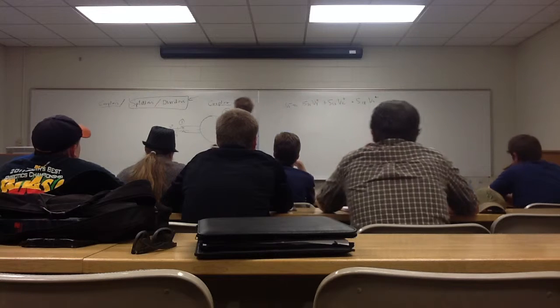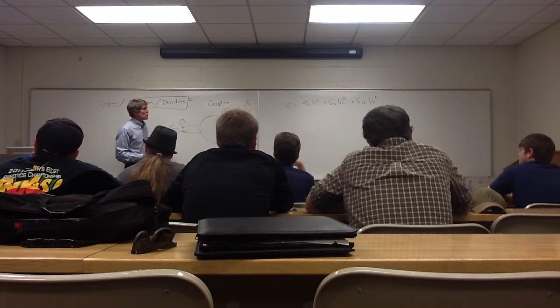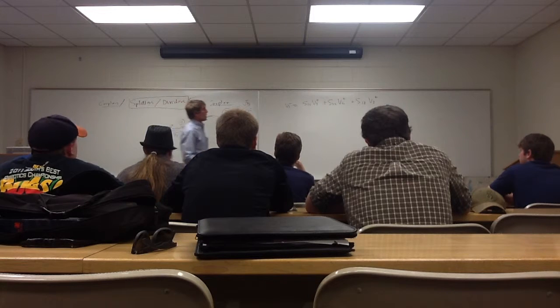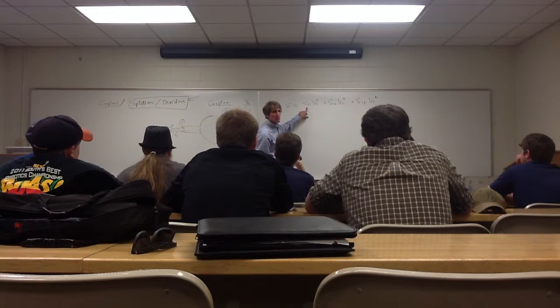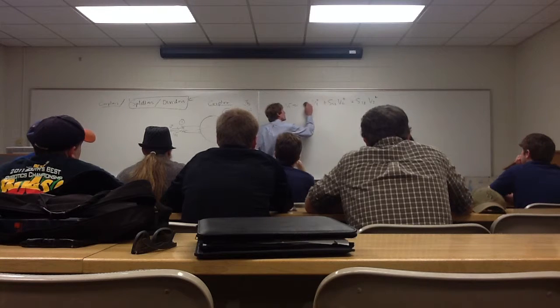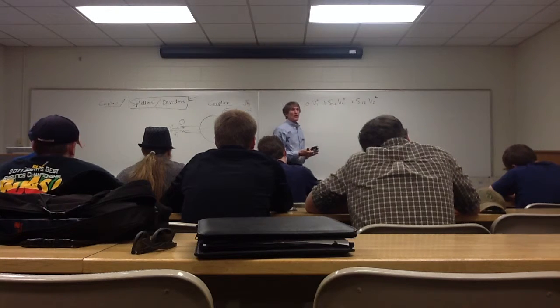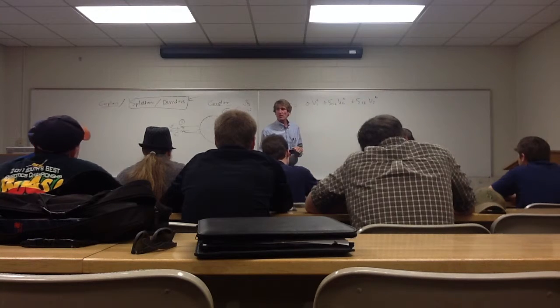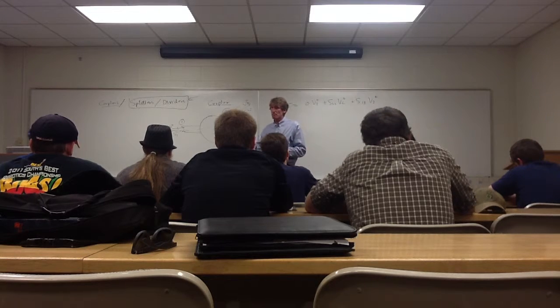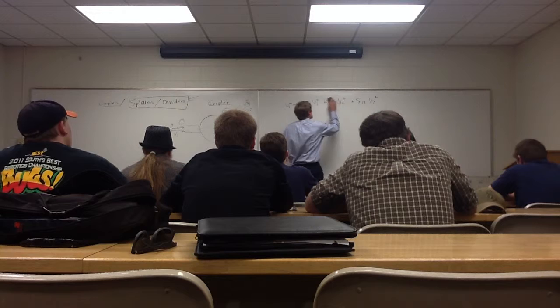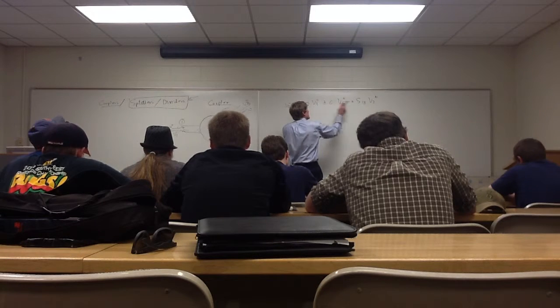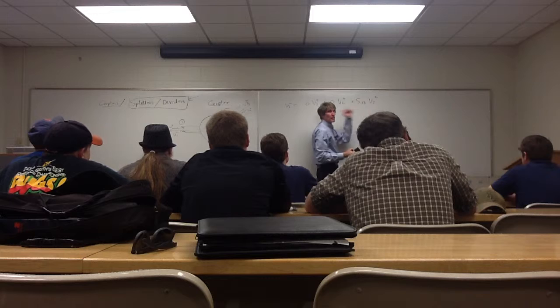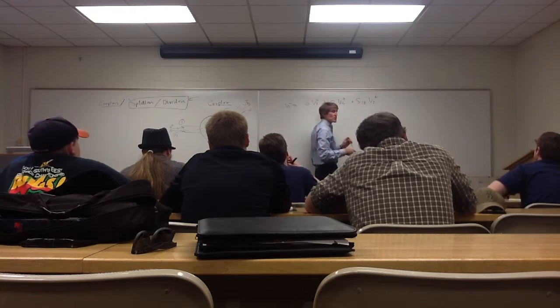If I take a look at this, and I come from port 1 to port 2, does this term matter at all? We don't really want any of V1 coming back, right? So ideally, this reflection coefficient right here would be 0. Here, for S12, we don't want any of V2 getting back out port 1, right? Take a look at that for a second. Are you all right with this, Emma? So this would be 0. Here, we want all of V3 to come out port 1. So this would be a 1.